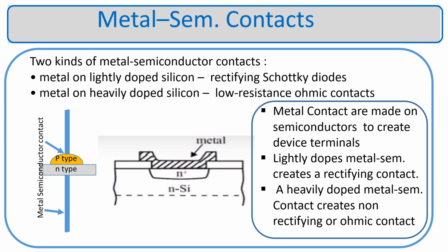In ASIC fabrication, metals are used to make surface contacts on semiconductor surfaces and create electrical connection to devices and nets. These dissimilar materials of different energy bands recombine and form a junction. Thus created junction exhibits electrical characteristics that are totally different from their native materials. A metal semiconductor contact formed by the annealing and etching process is called a silicide. The popular metal semiconductor contacts created are metal with lightly doped silicon, forming a rectifying junction contact, and metal with highly doped silicon forming a non-rectifying ohmic contact.